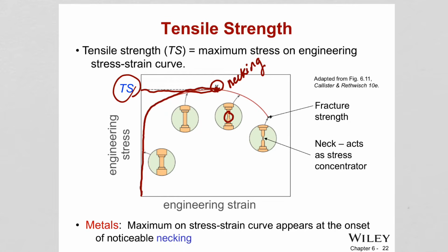Since the cross-sectional area is getting smaller, the device has to apply less force to achieve the same deformation rate. Remember, the device has to keep the deformation rate constant, but since it needs to apply less force now, because the cross-sectional area is lowering, what happens when you put it into the engineering stress definition equation?